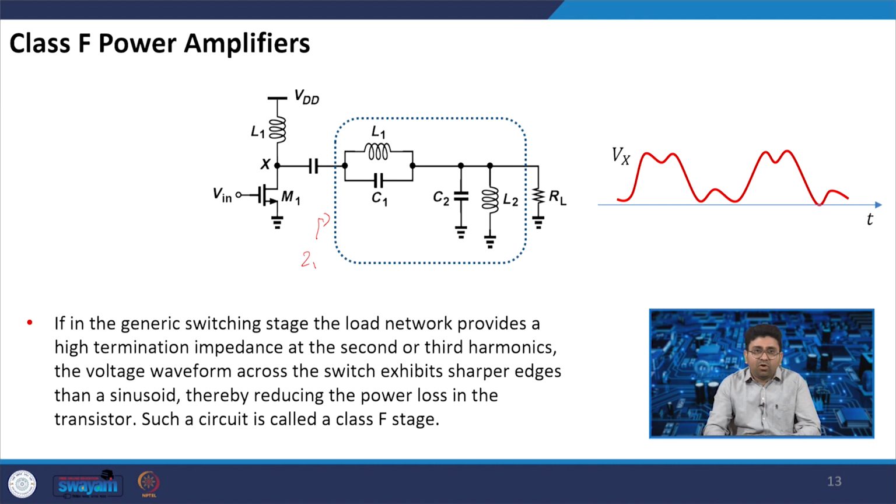So we have seen all the different classes of the power amplifier: class A, B, C, D, E, F, and class ABC, which is defined based on the conduction angle. Class D, E, F is about how digitally we switch and reduce the amount of power consumed by the transistor, and it improves the efficiency. In all these cases, the impedance matching network is very important for designing, and we have given enough time to understand the impedance matching during the initial lectures.